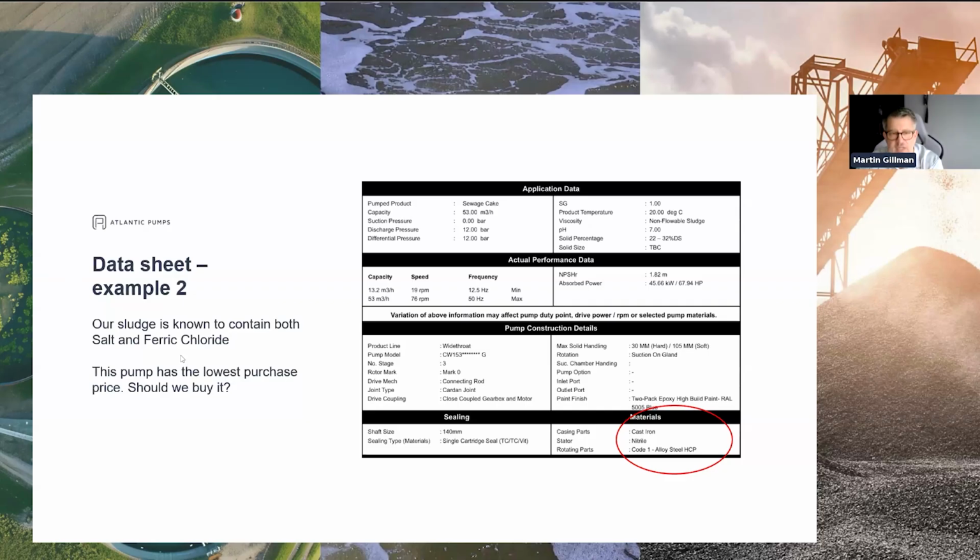If you are dosing any kind of chemical into your liquid, you also need to consider that when you look at materials of construction. It's not just the main thing you're pumping, because even the slightest contamination of certain chemicals will, or may, have a negative effect on your pump.